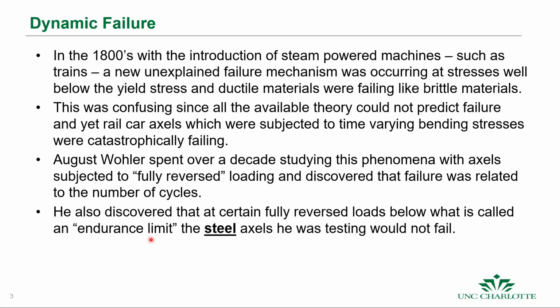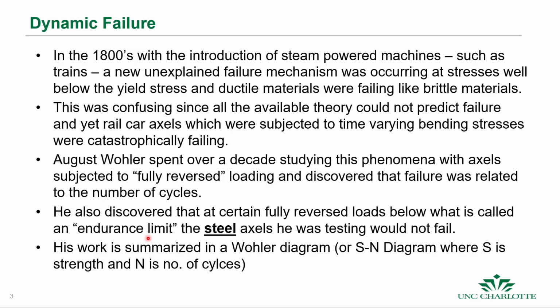And the endurance limit does show up in steel materials, but it doesn't show up in all materials. For example, aluminum does not have an endurance limit, and some other wrought materials do not have an endurance limit. And so we have to pick an effective endurance limit for those materials.